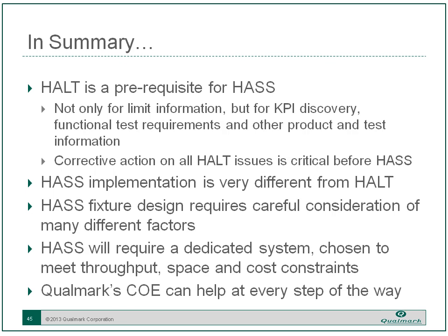So that just about brings us to the end of the webinar. In summary, as Chris described, HALT is a prerequisite for HASS. You have to have that done, not only for the limit information, which is critical, but also, as we described, the KPI discovery. It gives you a chance to see what makes sense and what doesn't make sense to monitor, what works and what doesn't work in functional tests, and what sensitive components you may have and how they're reacting and what to do about it.